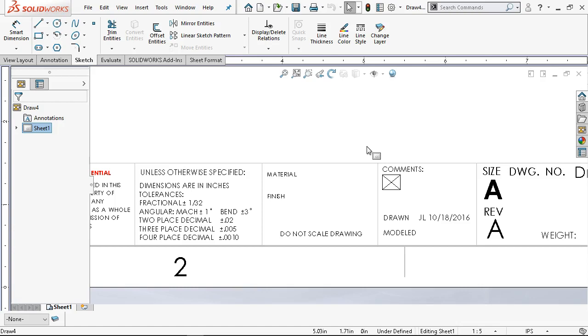Really we're putting those open tolerances, leaving it to be able to move, because we want it to be a fairly quick process. We want it to be a process that we can use maybe not the most precise, or the least precise tools, our turret punch, our notchers, our rollers, our benders, our finger brake, or the press brake, and not have to hit those numbers every time, but get good consistent bends if we're building boxes, making the corners and the hems and all those other fun things, to where it can be welded.